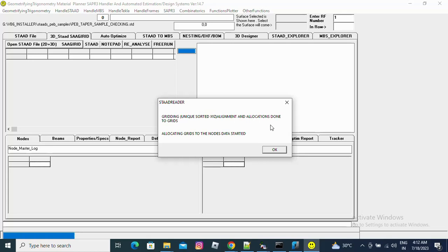The first thing here is the pre-assumption that the XY plane is taken as the end wall direction, and the XZ plane is taken as the side wall direction, because our longitudinal loads and lateral loads are followed in this way. The end wall has a different kind of detailing, and the side wall has a different kind of detailing in our Indian pre-engineered building structures, and if you need, then we can configure the whole thing in that way.